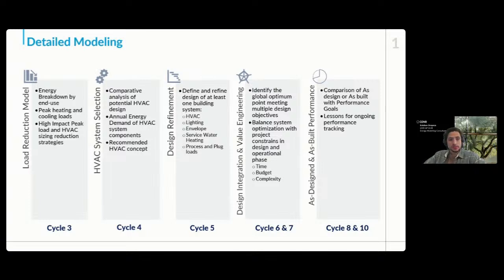This consequently follows to HVAC system selection. Once you know your peaks, your energy consumption profile and your thermal profile, you can start comparing different options and see how that impacts demand and the final annual energy consumption. Let's say this is where the more detailed whole year simulation starts to really have a weight. And so this will assess the project to set what the recommended HVAC concepts are.